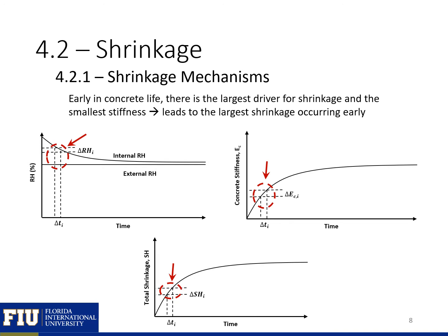This is highlighted again on this slide, where we can see that early in the concrete life, there's the largest driver for shrinkage and the smallest stiffness of our concrete. So this leads to the largest amount of our shrinkage occurring early in the concrete's life.